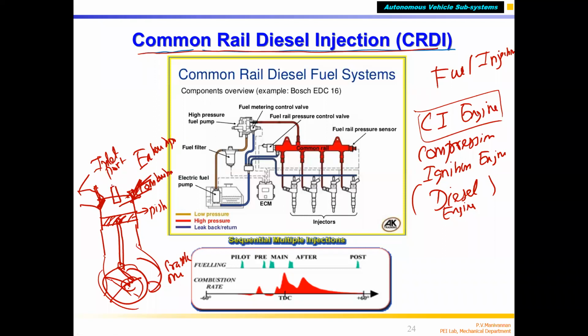No spark plug. So this is the injector, the diesel injector. High pressure diesel is supplied to the injector, and the injection is controlled electronically. It is solenoid based. Previously we had a mechanical injector. Now, in the latest generation, we have a solenoid injector.